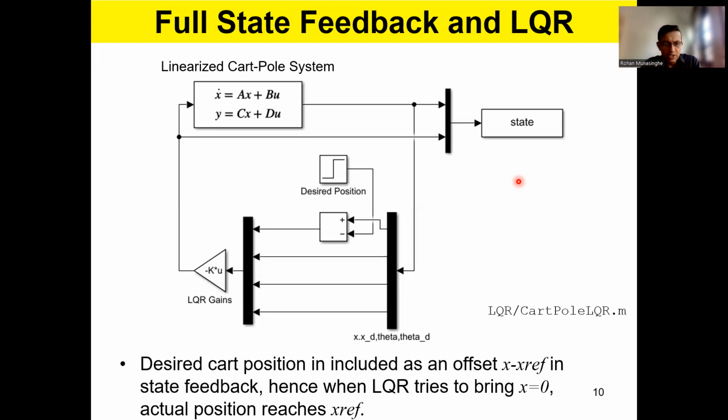Why don't you remember the state space, state feedback control? Have you forgotten that? Just a couple of weeks back. Pole placement regulator or state feedback control. That is one thing we can do, right? And the other one is, of course, you have not heard yet, LQR, linear quadratic regulator. Right? You can use state feedback control or linear quadratic regulator to stabilize the plant.